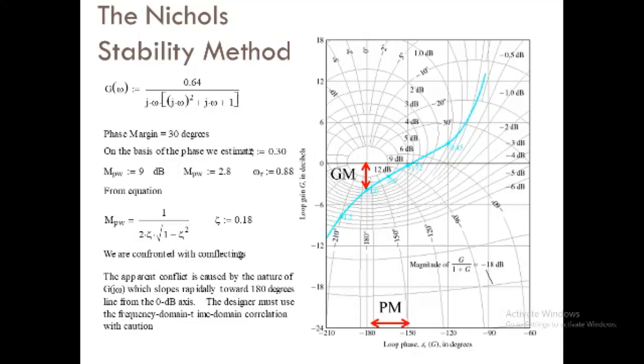This flat frequency response means that the magnitude ratio of the output to input is essentially constant over the bandwidth. Hence, signals in the audio spectrum are faithfully reproduced by a 20 kHz bandwidth amplifier.